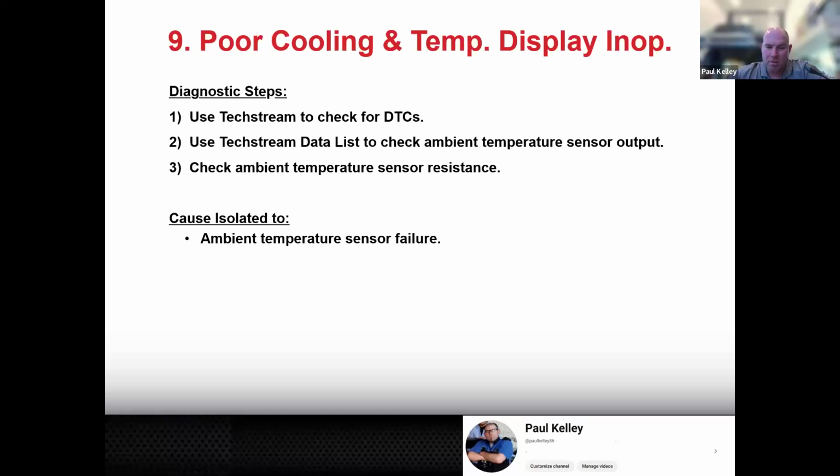Like if the temperature right now is 80 and the sensor circuit has an issue, on a GM, it'll actually say OC. It's like OC, Orange County. No, it's open circuit. They did something different. But with Toyota, a lot of times they'll just put 2 dashes. So if you see 2 dashes, it's more saying like, hey, something's wrong with this circuit, but it doesn't really know what. Now, remember, that's an input to the automatic HVAC system, automatic climate control.